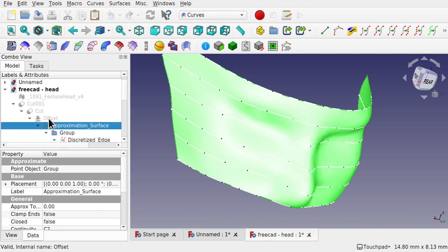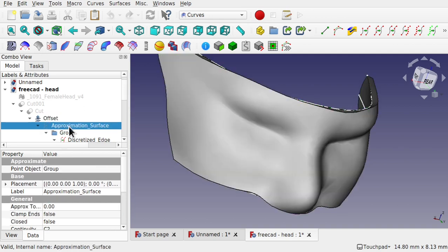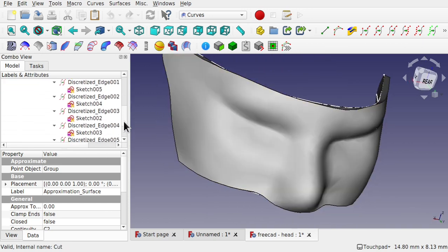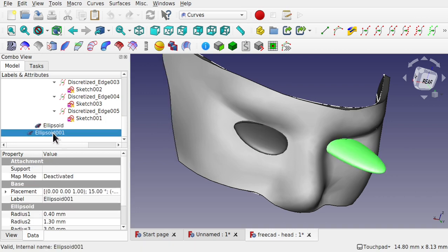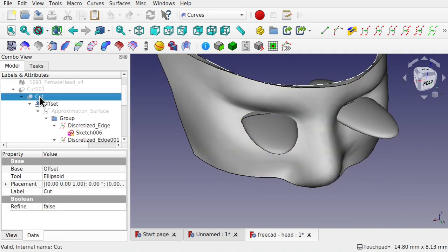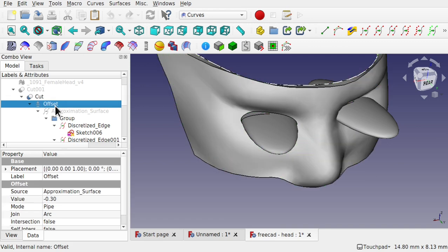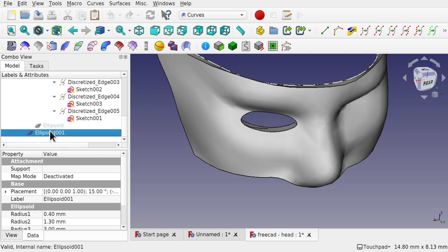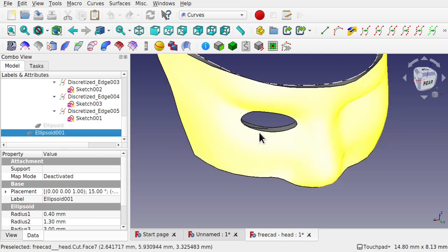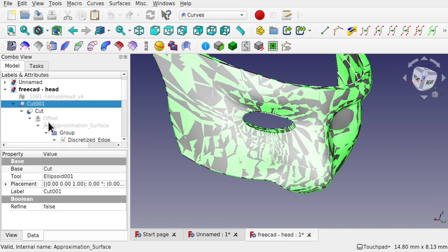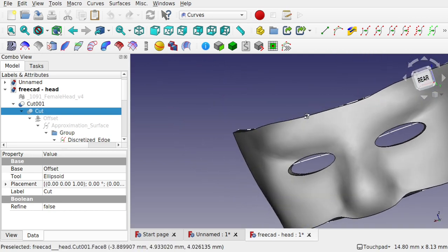And then what I did was an offset on that one. Create a nice offset there, like so. And then I'd use some basic Boolean techniques, because with that offset you can actually bring in other shapes like so. And from that I produced cut. Let's hide that and hide these ellipsoids. And we've got the secondary cut there, that one there, hide the other cuts, like so.